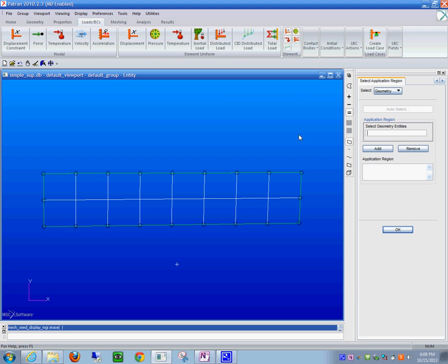here is a problem. You see up here, when you're going to select the application, if you click on geometry, it's just going to put on the whole surface, ignoring the finite elements. I do not like that. I want to do finite element model entities. So in this case, select the nodes, it says. I'm just going to select this too.